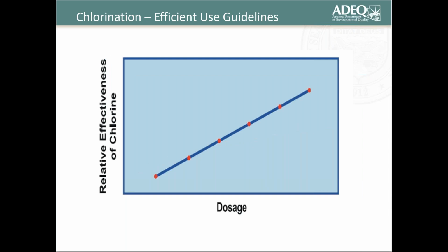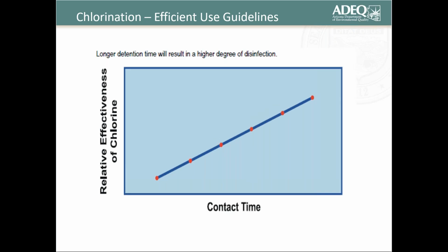Okay, dosage, and that's, I think, pretty self-evident. As you increase the dosage of chlorine, the effectiveness is also going to increase. And then the longer your detention time, the more effective your chlorination is going to be.